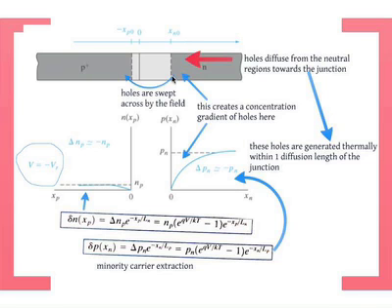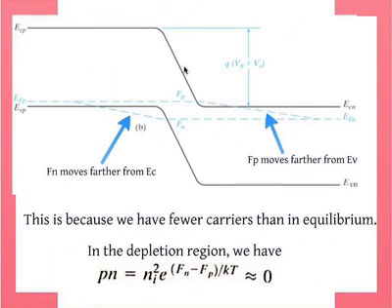In other words, you need to have enough holes near the junction to contribute to this diffusion. If they are far from the junction, they will not diffuse long enough to really contribute. So the generation that happens right near the junction contributes to the current. So that's why it's also called the generation current. This is the I_0. This is this thing right here under reverse bias, right? Minus I_0. That's also called generation current because it's determined by the thermal generation.